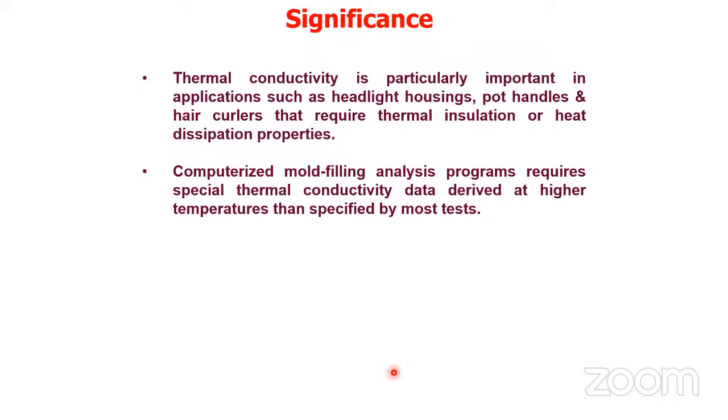Computerized mold filling analysis programs require special thermal conductivity data derived at higher temperatures than specified by most tests. So these applications generally require identifying what conductivity is there in that polymeric material, or how heat conductive that material is and at what level. That kind of identification we can perform using this kind of test.